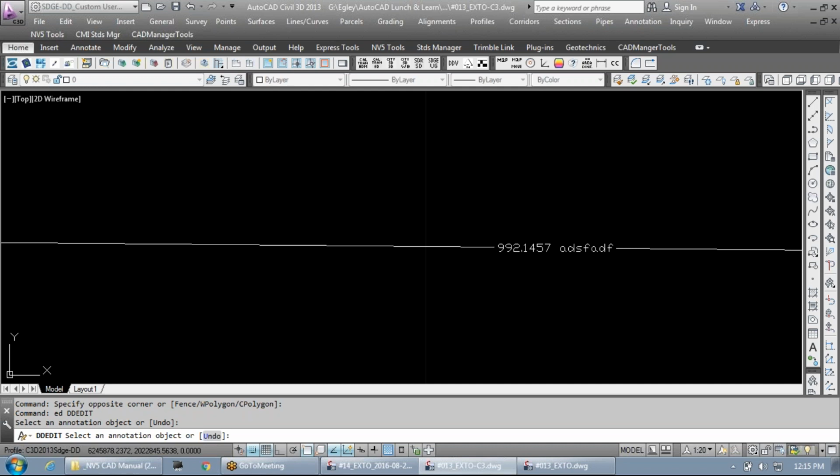We've had to completely redo projects because the files and the survey database were set up in the wrong zone. All right, so that's a lot of added hours, a lot of wasted budget on projects just because of one simple step. So bottom line, don't take things for granted. Go through the steps. The first step when you open a drawing is, what zone is my project in? So if I asked anybody in this room, current project you're working on, Rick? Zone 6. You should know the zone for every project that you're working on.